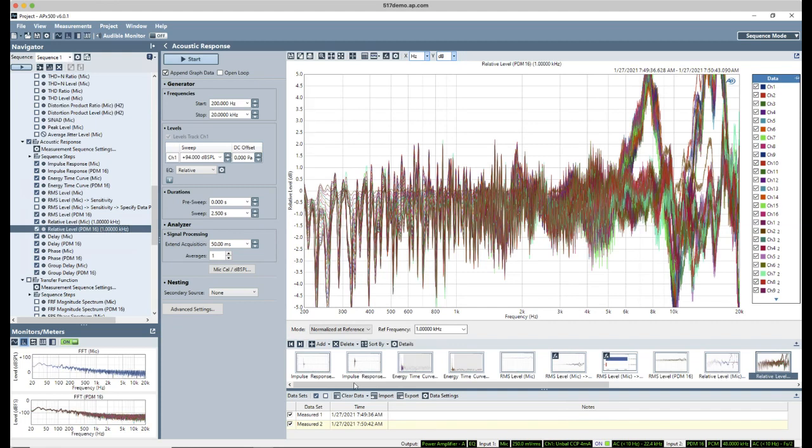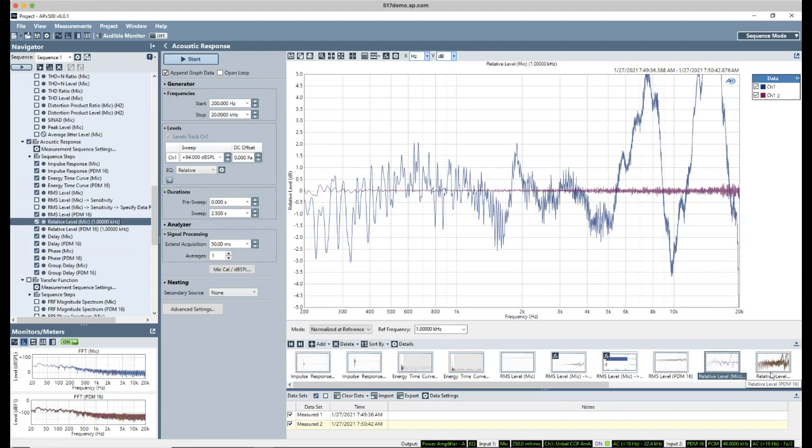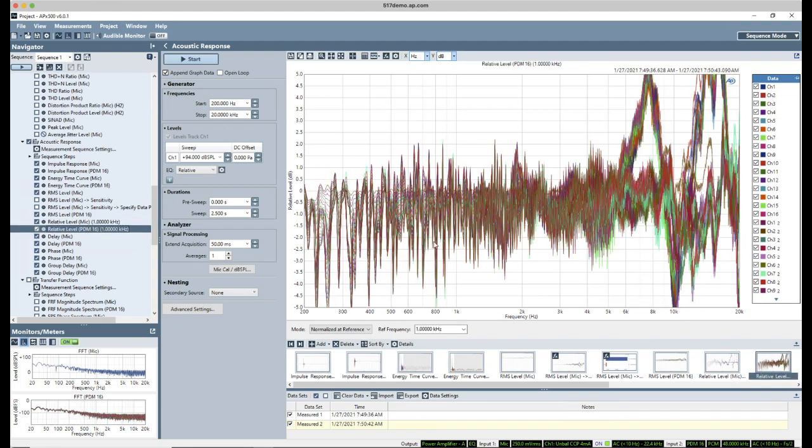you'll notice that our reference microphone has a pretty straightforward frequency response, but the frequency response, and this is somewhat zoomed in, has all these irregularities. And each of the PDM microphones is not perfectly flat. They have some volume, and so that does tend to give us a not perfectly flat frequency or phase response. Unfortunately, it's the translation from the idealized world to the physical acoustic world.